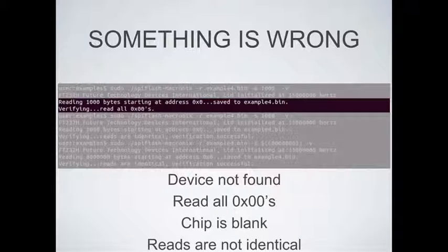Do you remember when I was telling you that the connector is very fragile and it kind of moves around on top of the chip? You might have to go get a lab partner or a coworker and have them hold down that adapter to your chip to make sure it's making good contact. If not, you're going to be getting this, reading all zeros.